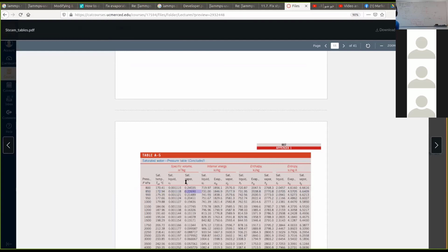So look for the VG. It means VG, UG, HG, SG. These are the best values. So interpolate between this guy and this guy to find the best entropy, which is somewhere between those two, but closer to this one. So you can get S2. You got it, guys? Can you follow me in the tables?